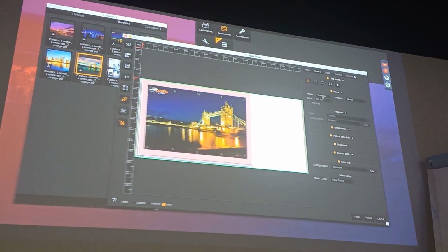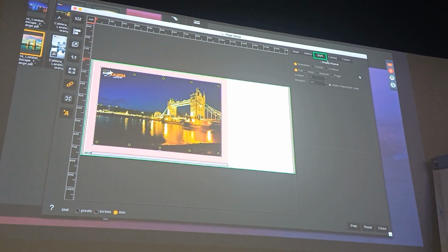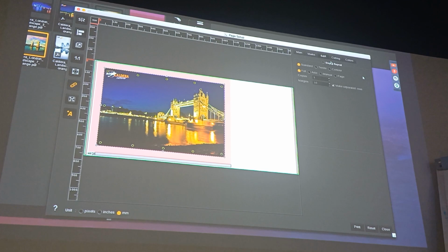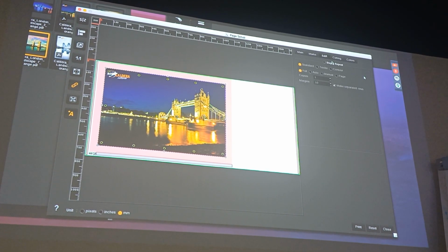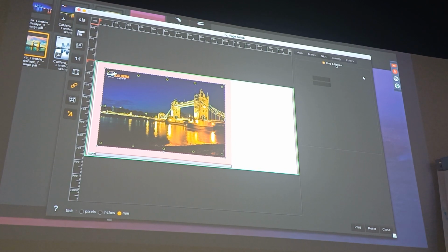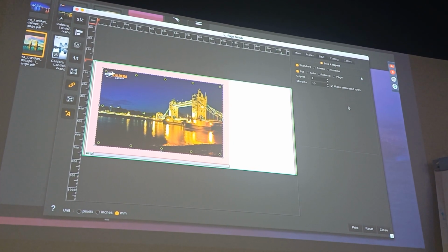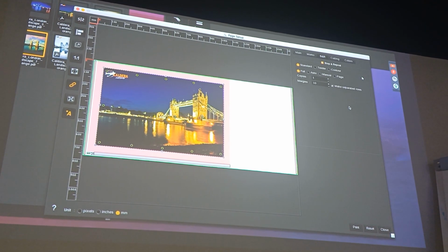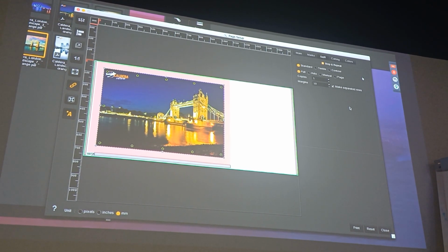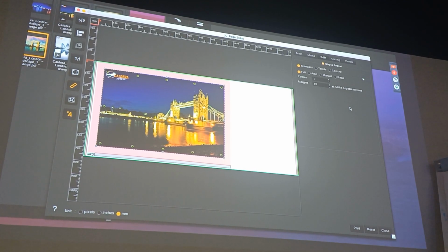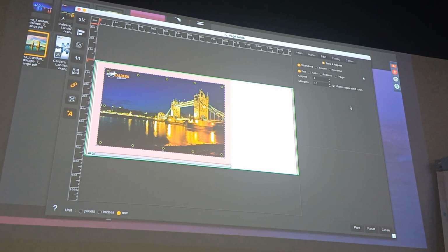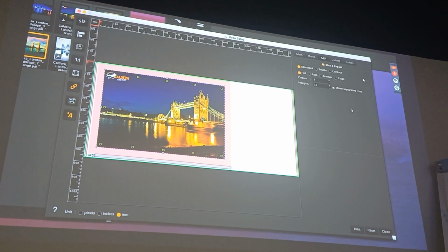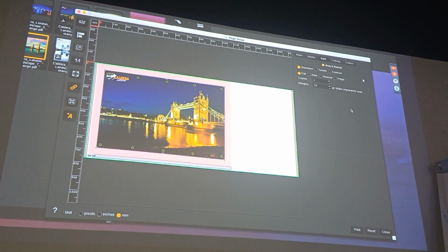Next tab is dedicated to step and repeat. As indicated by its name, step and repeat module allows to repeat the current image along a roll or a sheet format. After activating the feature, we can choose from 3 different options. We have the standard mode, then we have a textile mode, which is designed for smart textile pattern repetition, and the contour mode, made for optimizing the nesting according to complex cut shapes. In today's training, we will focus on the standard mode.